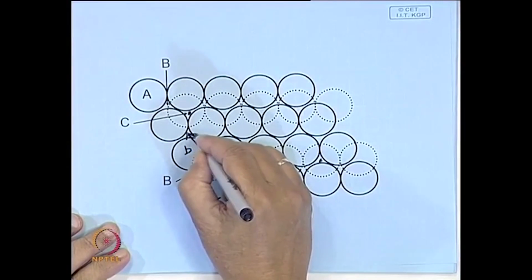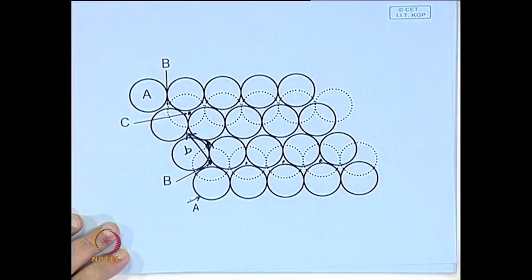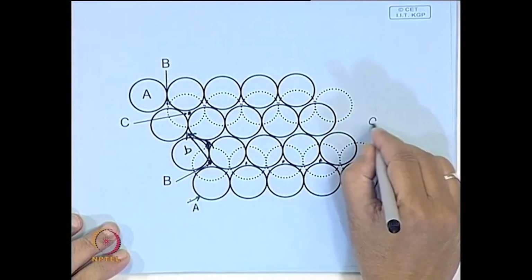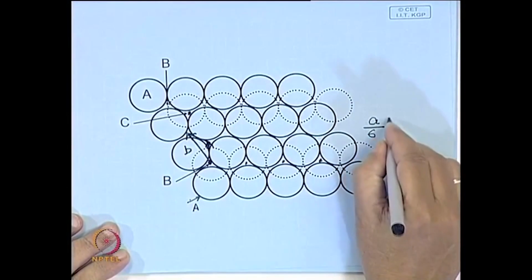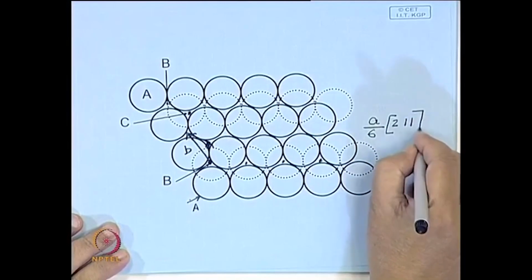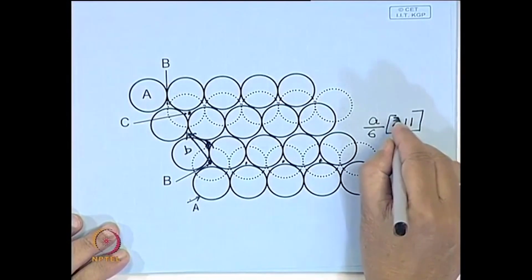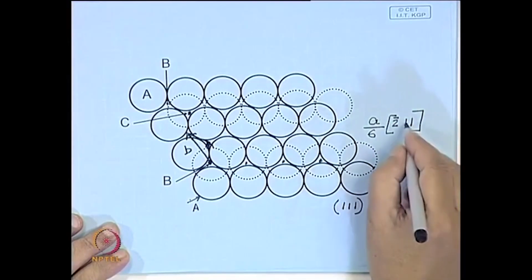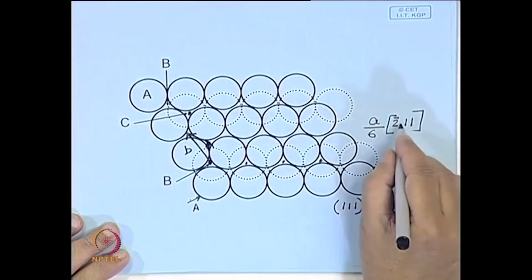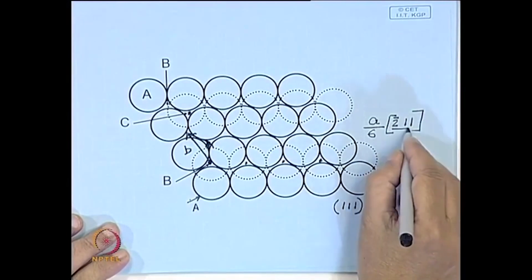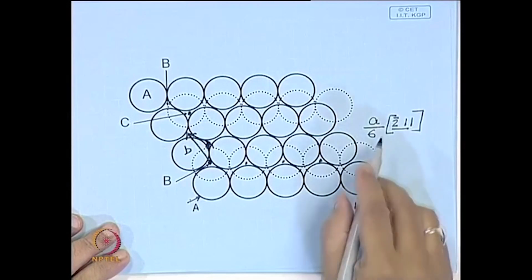and these are called partial dislocations, and their Burgers vector is of the type a/6 <211>. So, if this plane is 111, then the Burgers vector will be lying on the plane. That condition should be satisfied, that this direction should lie on this plane.